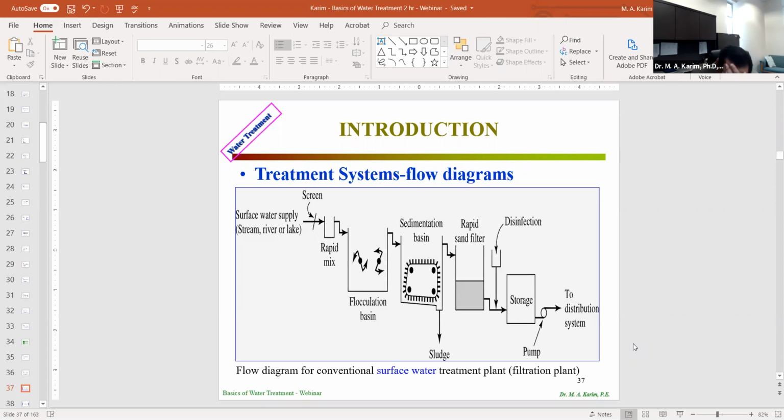Yes, most of the time, when we do the biological process in there, E. coli is not something that helps us do the process. It should be bacteria, viruses, and other things. E. coli is a pathogen. It doesn't really help us to remove the organics. But once we finish everything, the E. coli could still be there after the treatment of the wastewater. Then we need to do the disinfection finally before the treated wastewater goes to the river, because we don't want any kind of bacteria or E. coli or anything going to the river water.